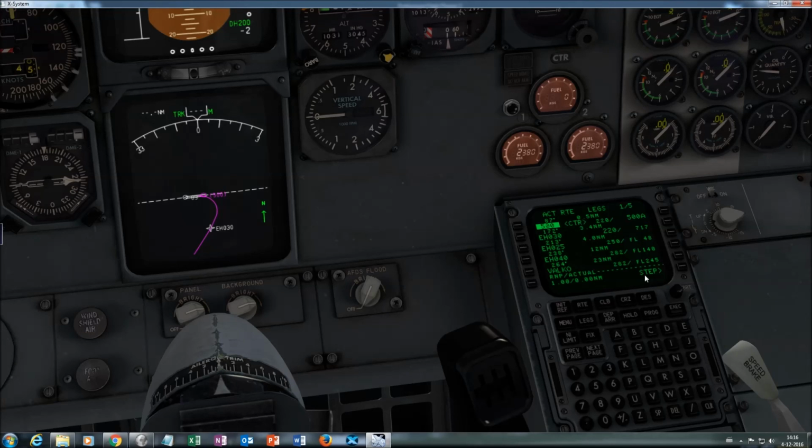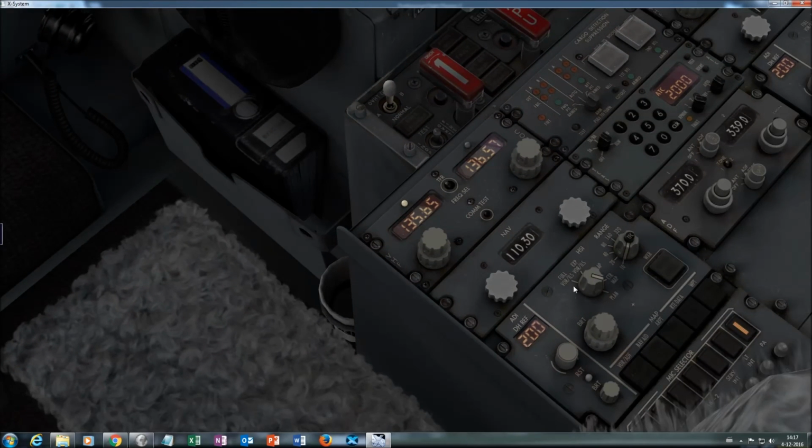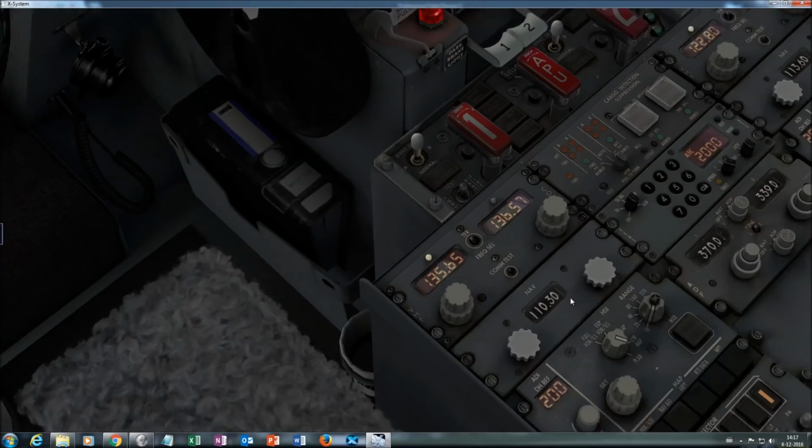When you set it to plan mode, you enter the step button, and you can use the lower right line selector key to step through your route. So from there to there, to there, to 40, to Falco, Gorlo, Refso, Xamon, Logan, Tripo, Sabre, Mango, Braso, Wesul, Lambin, Compton, Pomax, and then in the approach around Bristol. That's a very handy trick. Use that always to check your route and especially your arrival route.